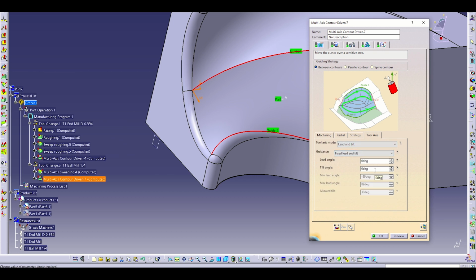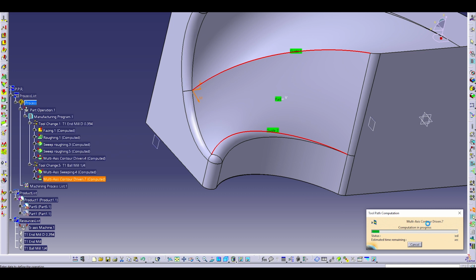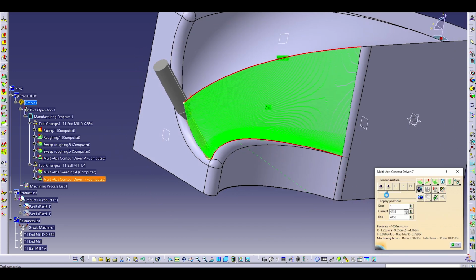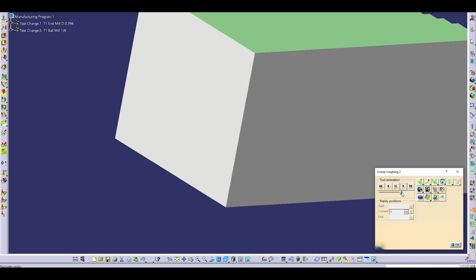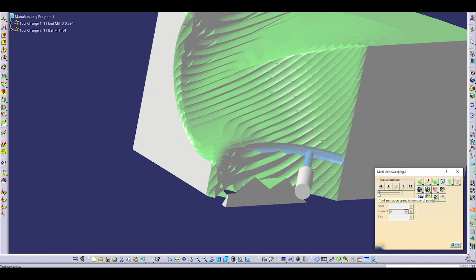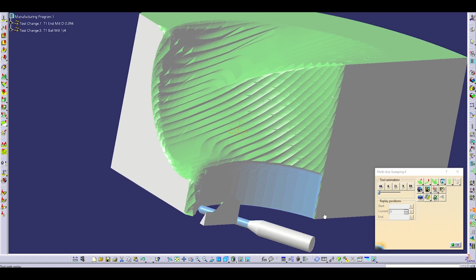And then, for 5-axis with the lead and tilt, you can kind of manipulate the tilt angle and the lead angle to really optimize the curvature and the smoothness of the tool on the part, because you don't want it to be straight on top of that ball end. You want it to just be tilted a little bit so you can get the perfect smoothness, I guess, milling the part there. Probably should save the video so I don't have to keep going back and looking through. But here we are.